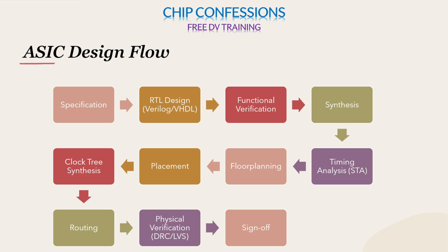Then what we see is the sign off. After doing everything, we will again be checking timing rules. Final checks will be done here: power analysis, timing checks, and whether signal integrity is maintained. Those things will be checked at this sign off stage. After passing the sign off stage, the design is ready for fabrication. So we can go for the fabrication which gives us the tangible chip we can touch by our hand.